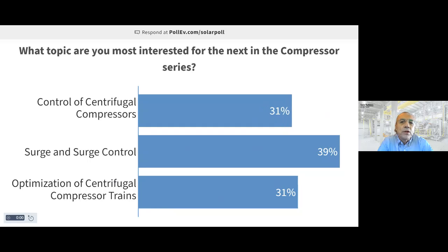The requirement is also that you do intercooling, because if you don't, the temperatures go higher than what you normally want from a process standpoint, and also without intercooling you would consume far more power. But you can make a train that does a pressure ratio of 30 on natural gas. And the reason why I'm emphasizing natural gas is because it depends a lot on the gas that you're compressing. These 3 compressors that I mentioned, all stacked with the necessary impellers, would get a significantly lower pressure ratio if you were to compress hydrogen, for example.